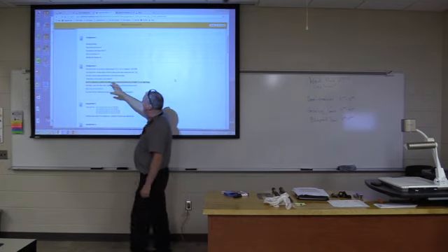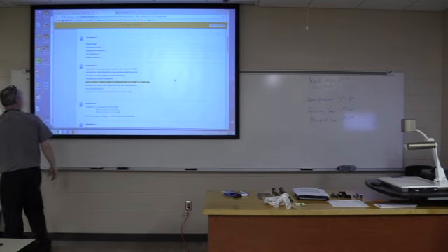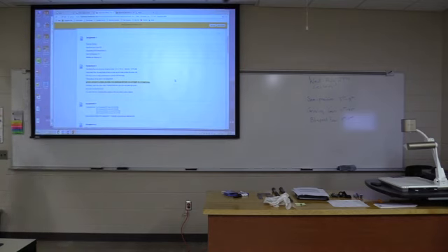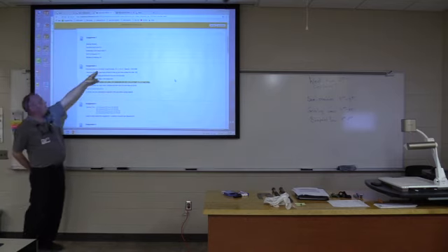But if you look at the description, it says horizontal bandsaw, 2 blocks, approximately 1/2 by 1 1/2 by 2, material equals 1018. Using hand files, file the large faces of the block to clean up and make the surface flat within 5/1000ths of an inch. That's using hand files. File 1 saw cut edge perpendicular to the top and the 1 long edge. And I'll have a block here and I'll show you that in a minute. But these pieces will be used in the next assignment. So you've got to do 2 of them, okay?